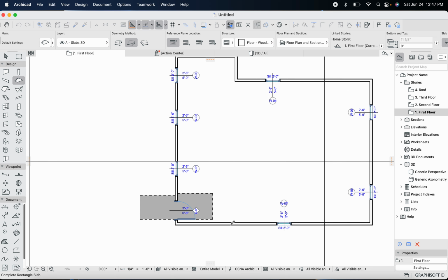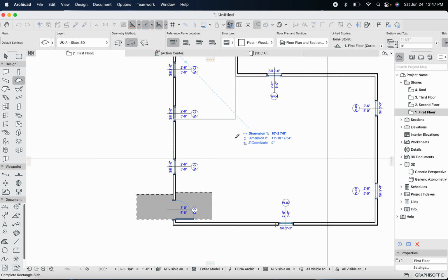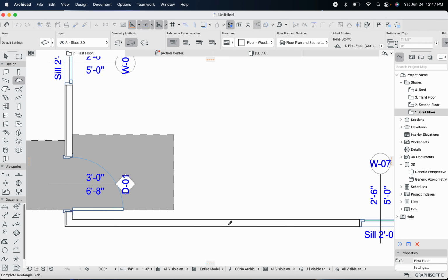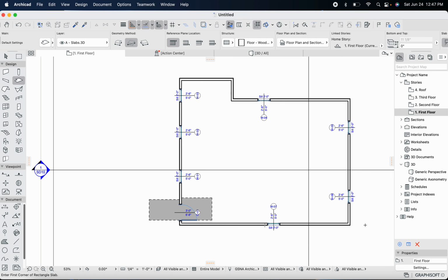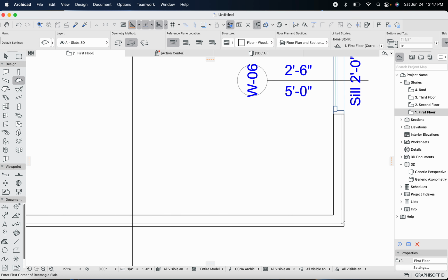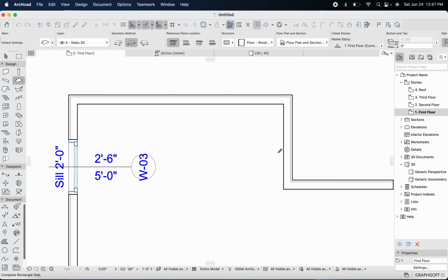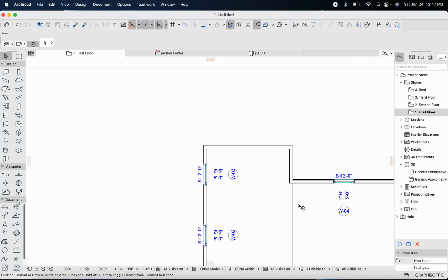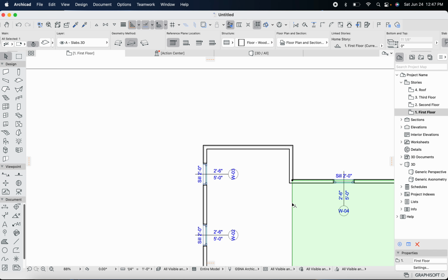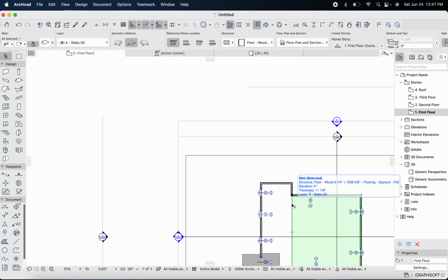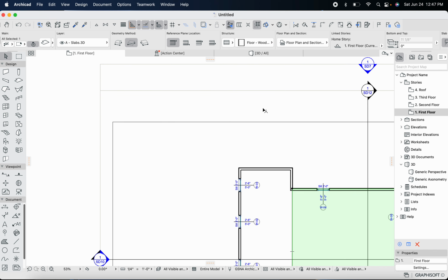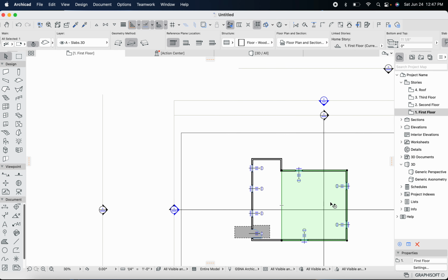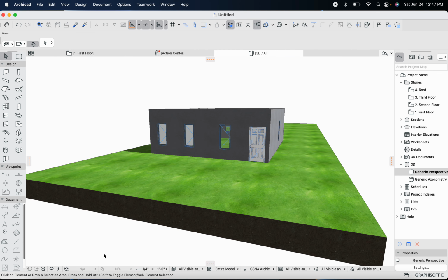So I'm just going to go ahead and draw the rectangle right over. Let me escape. Let's do it again over here. I want to make sure I get most of the. Click once, and then there's a couple things I can do here if I want to extend the floor, because so far I only have floor in this section of the house. Let's look at it in 3D.